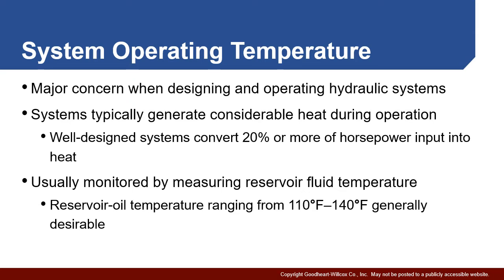Keep in mind, hydraulic systems do generate a decent amount of heat. If you're around hydraulic equipment or any mechanical equipment, you'll find that it's going to warm up. That heat that you're feeling is coming from the energy of the system. And even very efficient systems end up converting about 20% of their power input to heat. That doesn't necessarily mean it's only, say, 80% efficient overall. But keep in mind, there's usually a lot of downtime in hydraulic systems where they just operate, not necessarily moving anything at that time. And during that point in time, essentially all the energy is going to be converted over to heat.